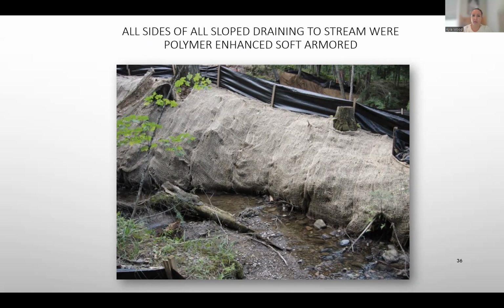We didn't apply polymer to all of these areas. One thing to note is that in Michigan, we have a permit that we can apply for, which is a Rule 97 permit. In most states, and I think in the federal CGP, you are not allowed to apply flocculants directly to waters of the state, and you need to collect the flocculant. So in this case, we were applying the polymer essentially on the banks of these streams, and so we had to get a special permit.